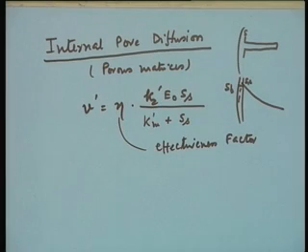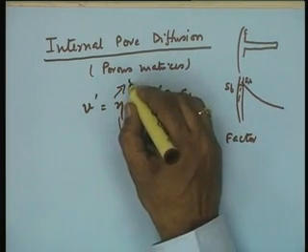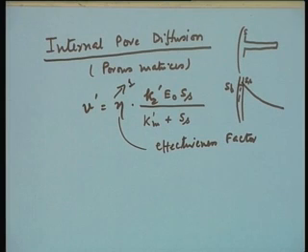And usually in most cases, as per experimental experience, a particle size of about 30 microns in most biochemical reactions has been considered to give you an effectiveness factor of 1. Essentially you will see from this relationship that the maximum effectiveness factor can be 1, because that means you have an enzyme reaction rate under the conditions when the whole enzyme particle is flooded with the substrate, the same substrate concentration present at the surface is present across the particle, at all the pores, and under that condition the effectiveness factor will be 1.